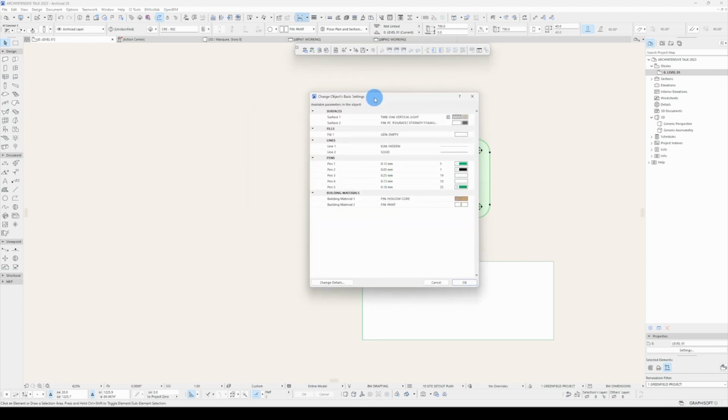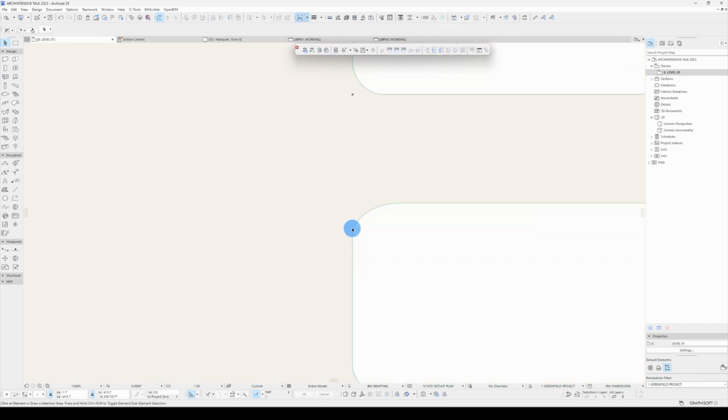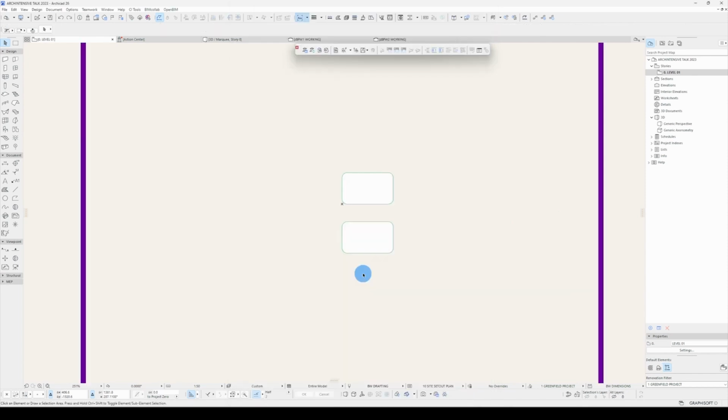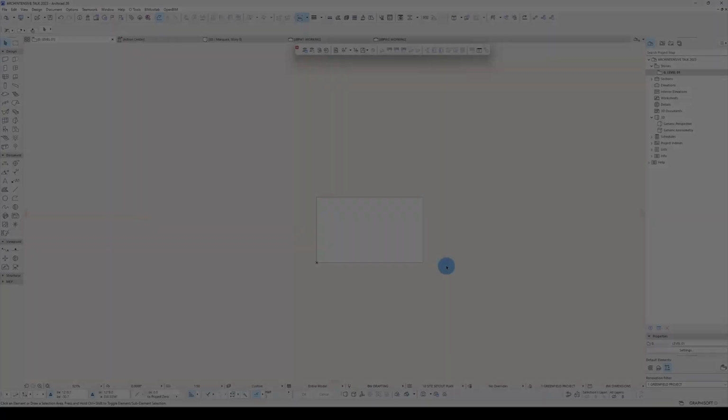And you can see with the dialog I've been presented with, it's reset any parameter name changes I've previously made. Once again, you can see that this has just applied a scaling to the entire object. And if I open the object settings, my preview picture has gone. So that is technique one of this save as method.